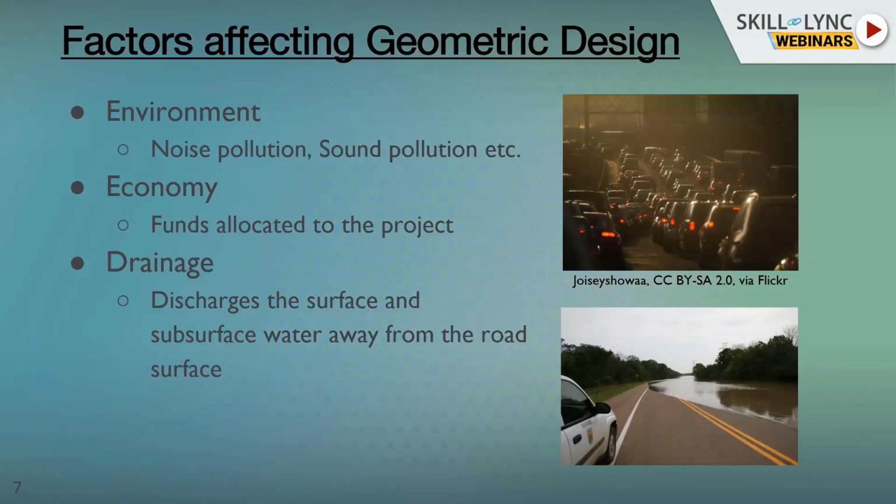Do you know why? Because we don't have a proper drainage system. That is one thing, and the other thing is we might be in a low-lying area. As a designer, you are responsible. If a water droplet falls on the road, how it is traversing, to which direction, to which culvert it is going, to which stream it is merging. You should have that much confidence about where this water is going. Water is the first enemy of the road because it can destroy it completely.